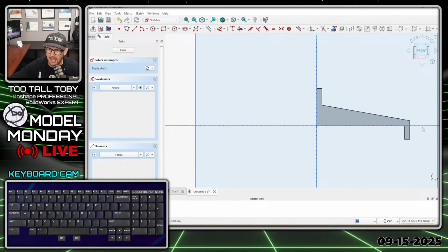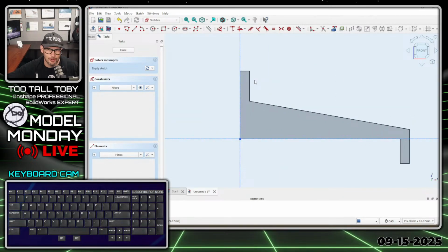Now in FreeCAD, what I believe you need to do to reference these edges, and I could be wrong because I'm still kind of a noob, is click on this icon here, Create external geometry. So I click on that icon first, and then I pick this edge and this edge, and then I can jump into the polyline command and reference those endpoints and that geometry in FreeCAD.